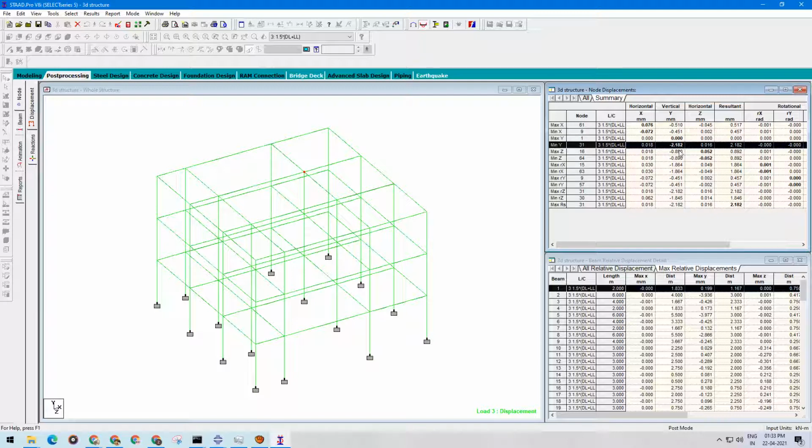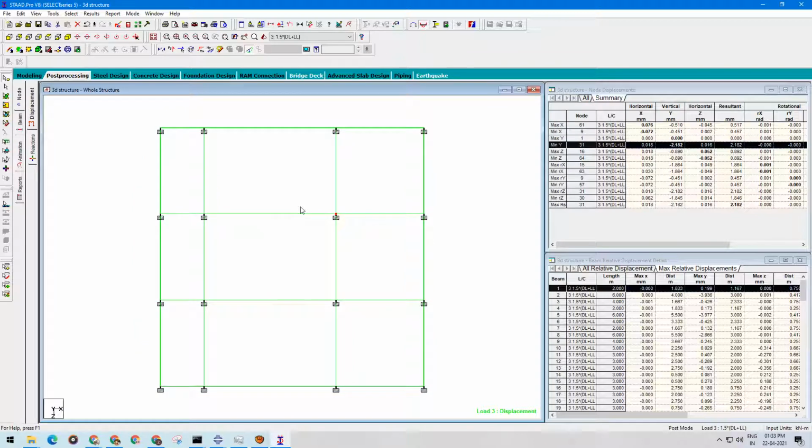Okay, so this is minus 2.182 mm in vertical y direction, and it is acting at this node over here. Okay, so automatically, because this would be the load, the load will be maximum. And also you will see that on this column the foundation load will be maximum, because you can see over here this is the most loaded column in the entire structure. Okay, this and this one and this one. Okay, so that's why it is having this vertical deflection over here like that.